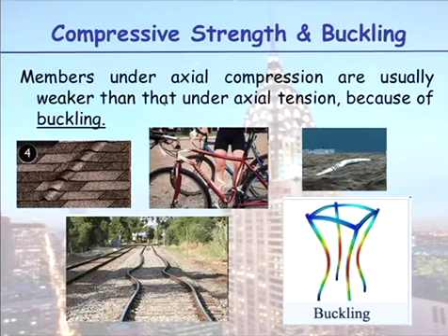When do we get buckling? When you smash your bike. Trying to make this more interesting for you. In the desert when it's really hot, due to thermal stresses, not being able to expand, your pipes will buckle. Here's your railway track again, a very, very hot day when all those trains go out of service. Could be because the railway track is buckled. Or here is a finite element analysis of a tower supporting a weight, and the mode of failure here is buckling.